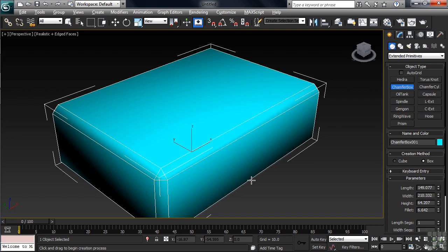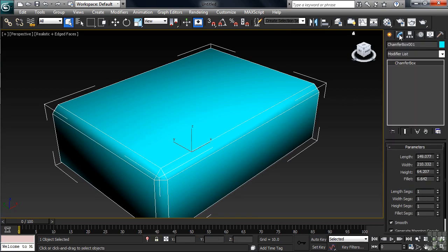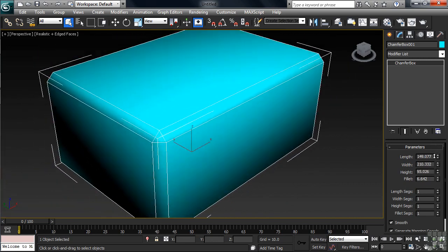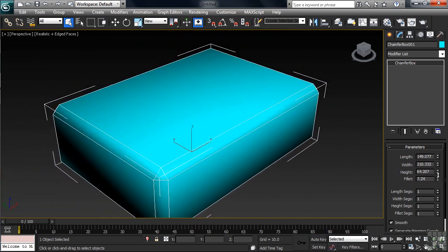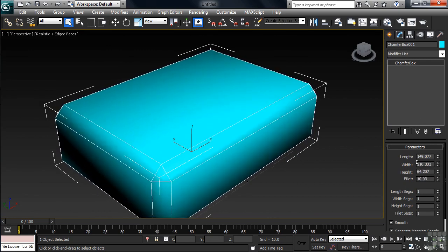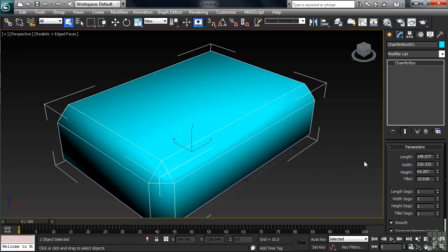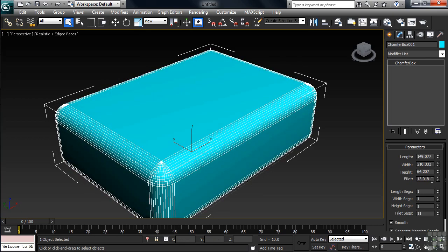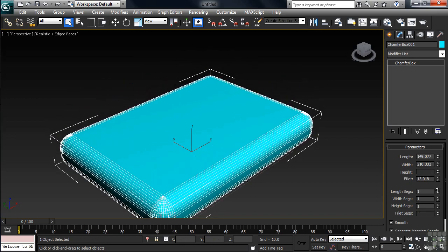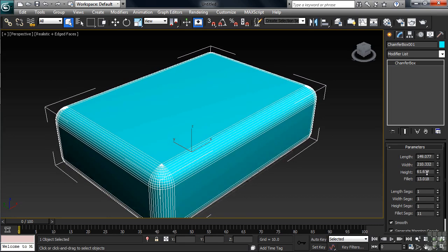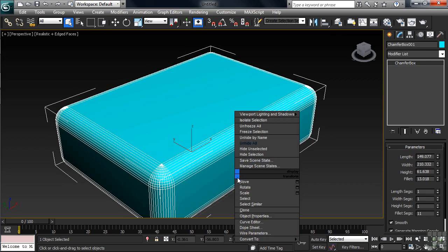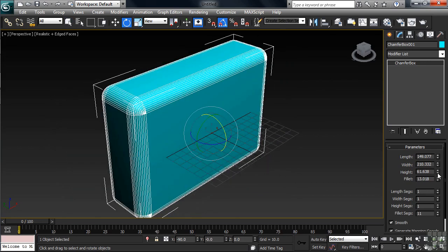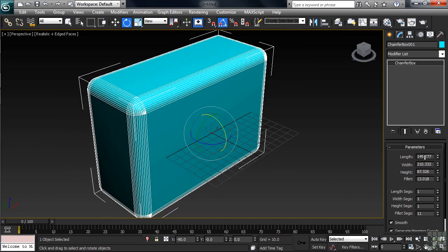Now we can cruise on over into the Modify column. Like with a normal box, you've got your regular length, width, and height settings. You'll notice, though, that below height you have an adjustment called Fillet. That'll control the size of our beveled edge. In order to be able to create a rounding effect on the edge, drop down to the segments, changing the fillet segs. If we lowered the height, we could have anything from maybe a credit card or an Apple iPod. Standing on edge, we'd have ourselves the body to a suitcase. So a bunch of different things that you can create with the chamfer box.